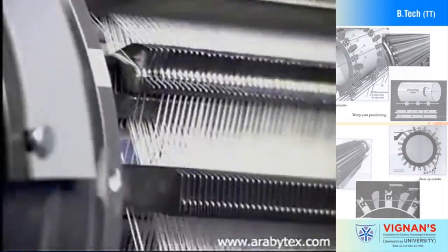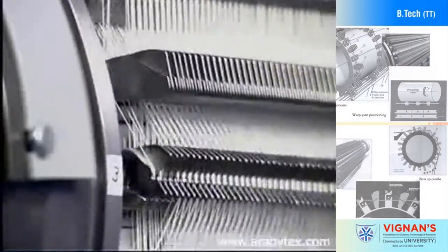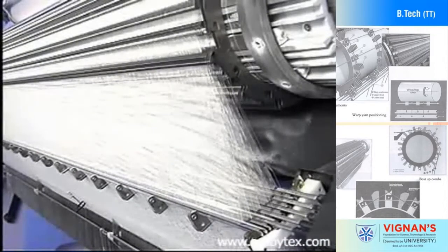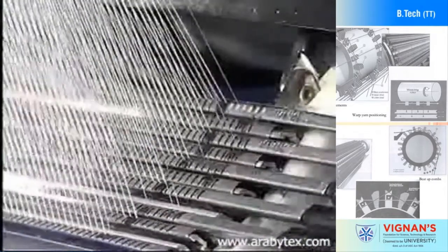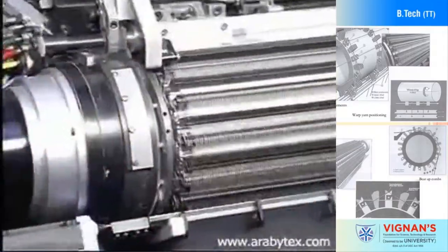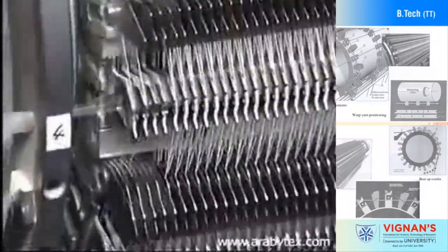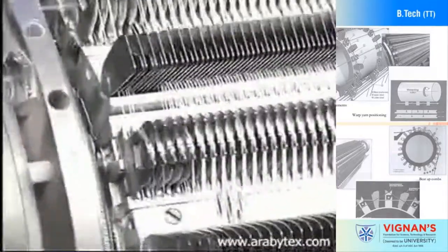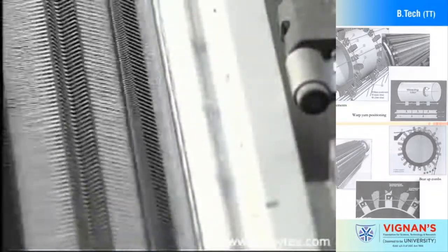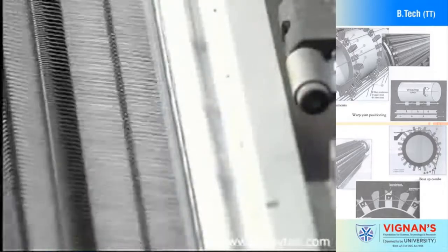Shedding is an important motion needed to form the fabric. Shedding involves separating ends from the warp beam into an upper and lower shed. The space between the upper and lower shed creates the path needed for weft insertion. After insertion, the shed closes and the weft is beat up into the fell of the cloth to form the fabric.